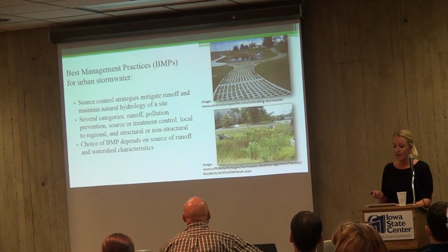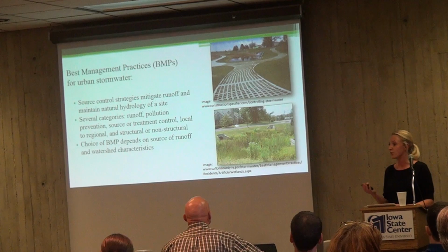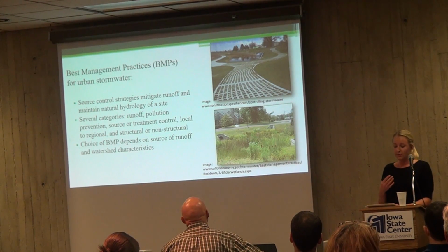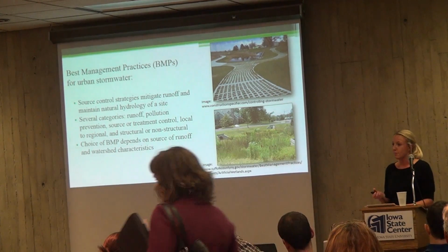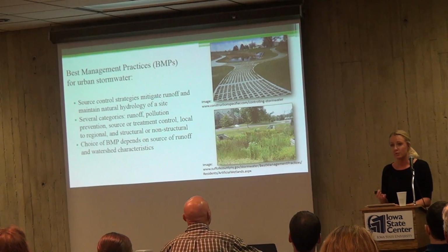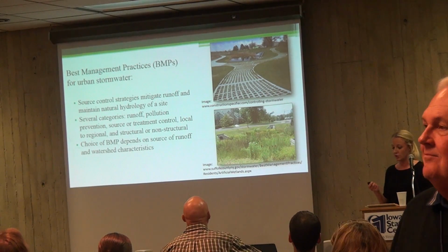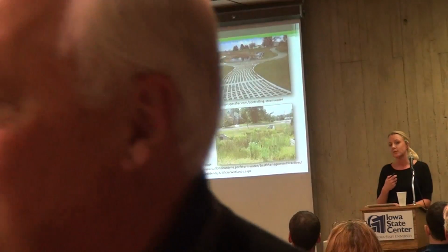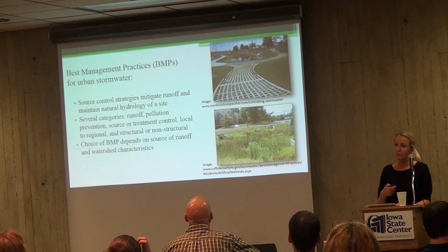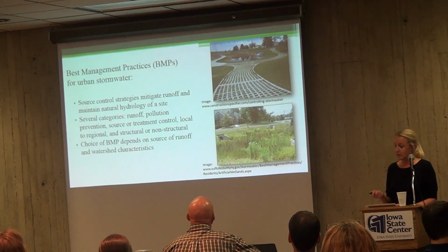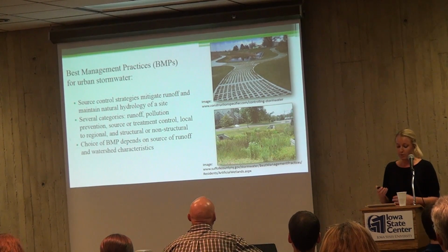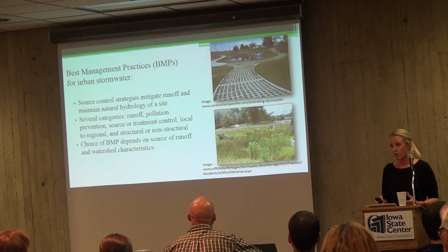In terms of selection, designers must take into consideration the watershed terrain, community, environment, as well as location and permitting factors. In areas of great urban density, available space for BMPs can be an important constraint, and the range of space required to implement such BMPs is quite variable. When using vegetation to promote infiltration, designers must also consider strategies that are aesthetically pleasing to the community. Understanding which functions of stormwater control, whether it's infiltration, water retention, chemical absorption, or evapotranspiration, are most appropriate for a site depends on the characteristics of the watershed.